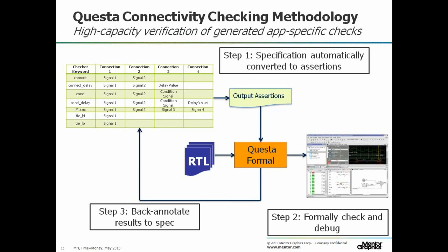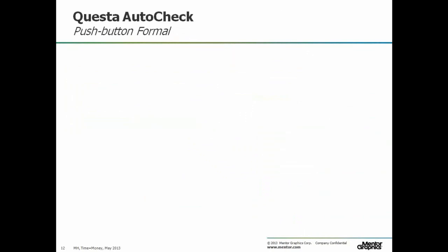You can do reset connectivity checking, clock connectivity checking. So you may have thousands of clock enables, checking that when you supply the right control signal, all those enables open correctly and you get the clock waveform propagated through. So formal verification here, at a high level, does a very constrained verification of the wiring or the connection in your device. And then we get into some of the corner case behaviors.